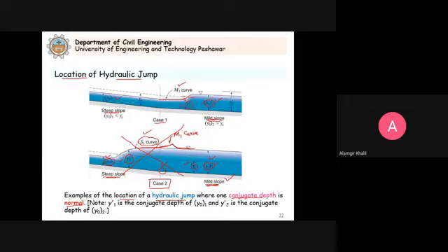This y1 dash that we calculated here, this is shown here. You see, it is not possible. This y1 dash is not possible, because the water will flow with the normal depth here. So it means that this is the possible condition. You have M3 curve, then after the break, this hydraulic jump will occur, and the water will then continue to flow on a mild slope with the normal depth, this one here. So it means this is the possible profile, and this is the correct situation.